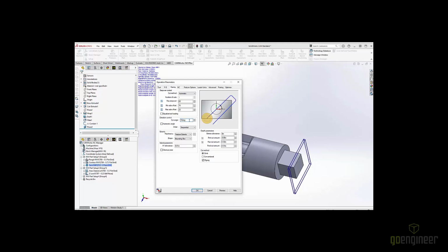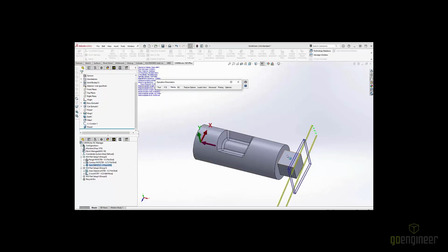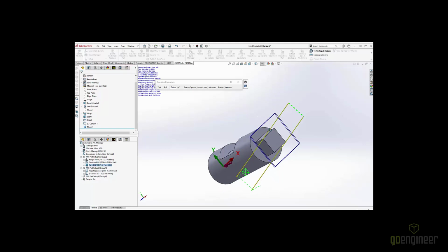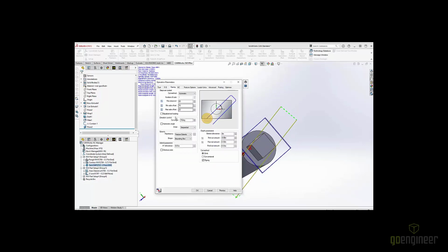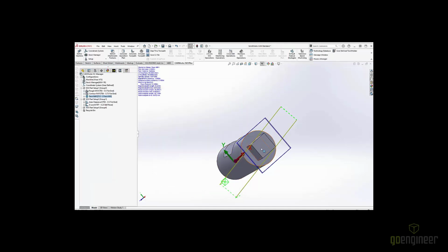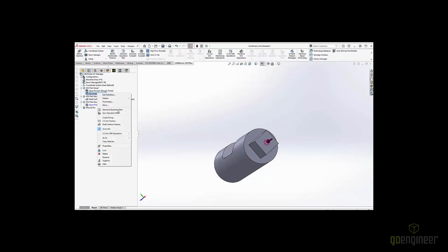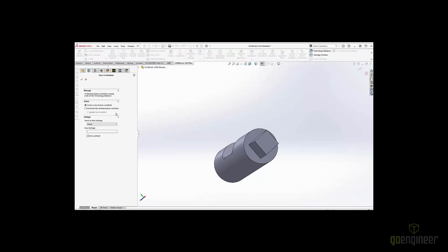Right now it's set to 10-degree cut angle. You can see that represented on screen. And maybe I don't need that. Maybe I just want to switch back to 0 degrees, keep it simple, update my toolpath. All right, now we're going straight. That's not a change I want to make every time. I can jump back to my feature, save that updated strategy.